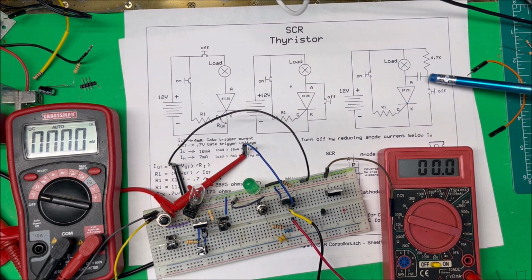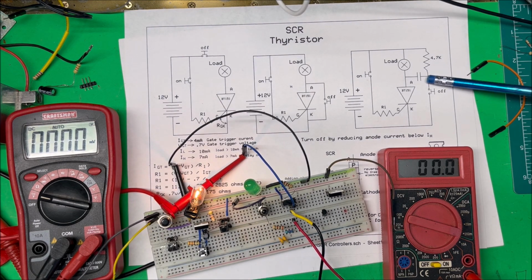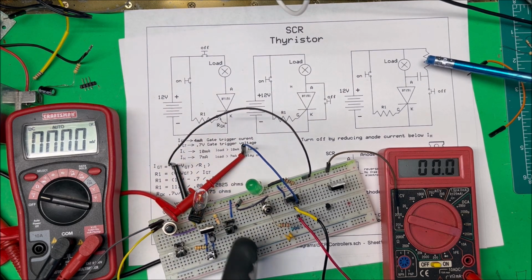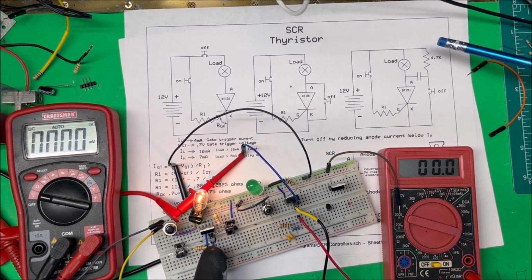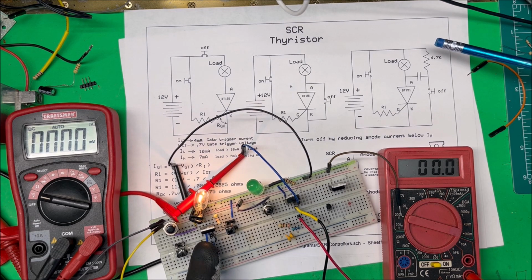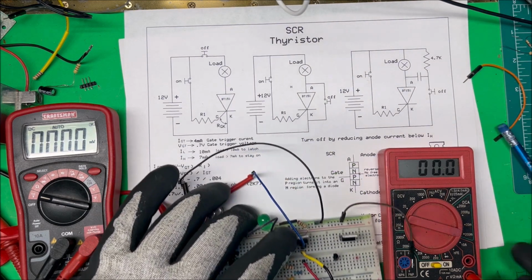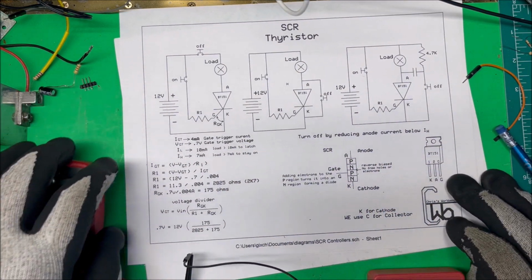And then the other way to do it is to have a capacitor across here with this 4.7k ohm resistor there, and we turn that back on, and then I can push this button here and take that resistor to ground and turn the unit off. Okay, I like that method the best. It goes off immediately, and this one here, of course, as long as you hold it in, it's on. But this way, it turns off immediately. And so that works out good. So that's the 3 ways to turn it off.